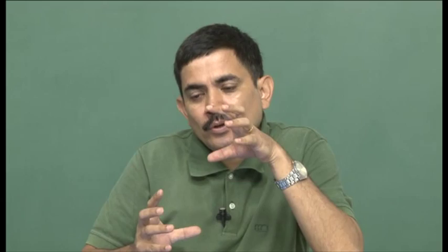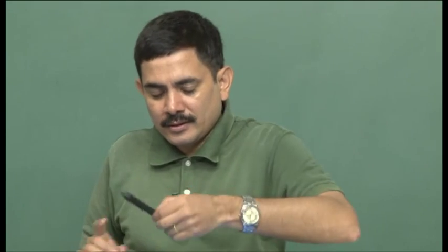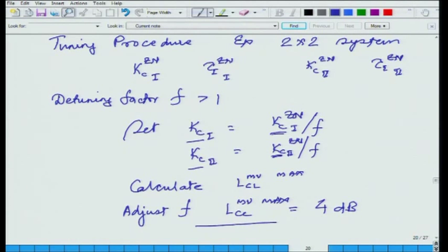So, what metrics do we use to reject bad pairings that lead to interaction terms that are, well, what should I say, I am struggling for a word, but maybe not good. So, we want to characterize the severity of multivariable interaction, and based on those metrics, we should be able to figure out, okay, for these pairings the interaction is bad, for these pairings the interaction is not so bad. So, these pairings are worth considering, those pairings are worth throwing out the window.